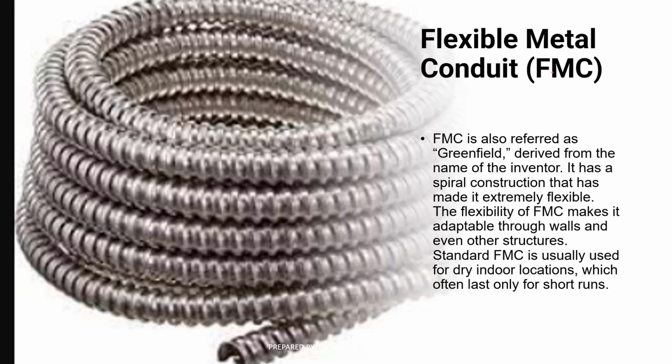We cannot avoid the bends in a structure or building, so we need to follow the corners, and we are using flexible metallic conduit. The latter makes it harder to bend regular conduits. The RSC and IMC are harder to bend, so the best option is the flexible metallic conduit. Lights, attic vents, and water heaters are common examples of basic flexible conduit installations.